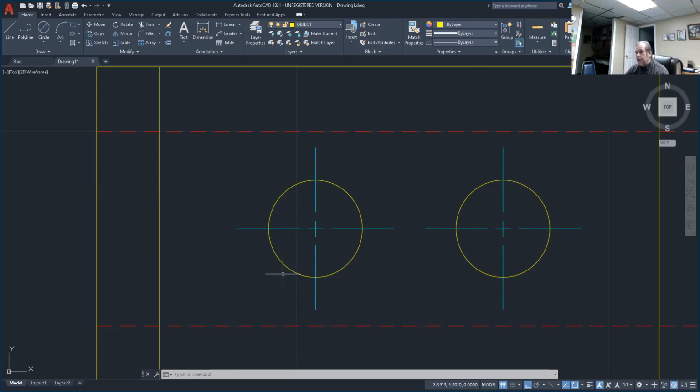Now, one thing I want you to do here to finish up our top view, once we do this, our top view will be completely finished. I have two circles here. How do I know that they're aligned? If I do not connect these center lines up, they could be misaligned a little bit. So I do not want to draw another line here. I'm going to click on one of these lines, either this one or this one. You're going to get three boxes. I'm going to grab the end box and bring it over to the end point right there. So now they're hooked up together.